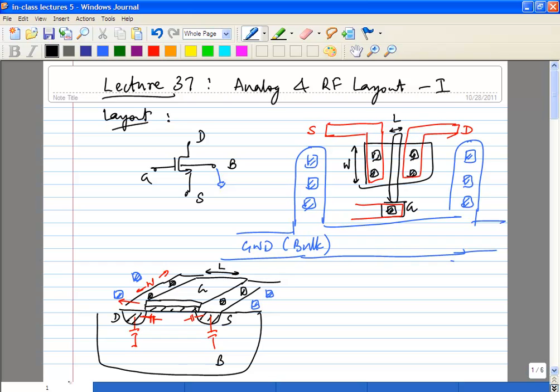You can make the same thing wider. Now the only thing you have to be careful when you do all these things is, you have to worry about parasitic capacitances. Typically these parasitic capacitances will be to the gate, or to adjacent lines, and these things may not be modeled very well. You have to be a little bit careful because even in your LPE step, the layout parasitic extraction step, there may be cases where, for example, capacitances on top of the transistor to the gate, there have been cases where people have got burnt.